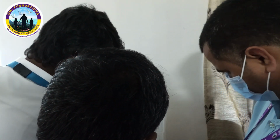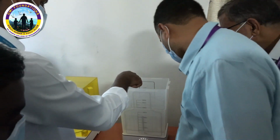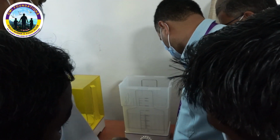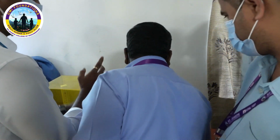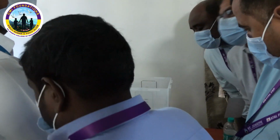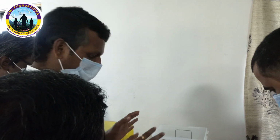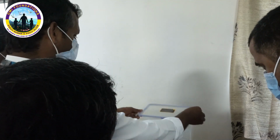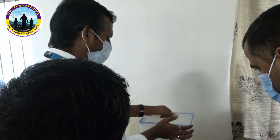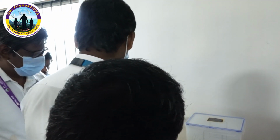So here we have to set the time, how much time we have to run it. Once you run it, there is a magnetic stirrer that will rotate. Liquid should be there. It will rotate and keep washing the component like a washing machine. So all the excess resin over the part will be removed, and it goes with the IPA. Once washing is completed, we have to remove the support structures manually, using the pliers.